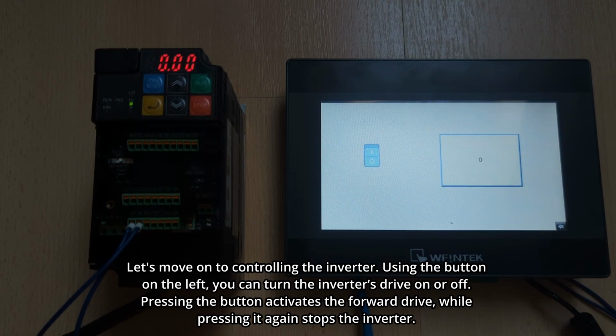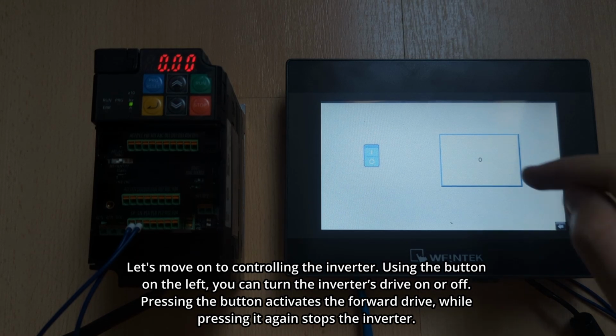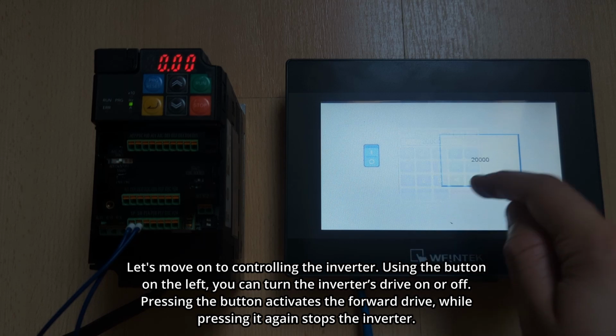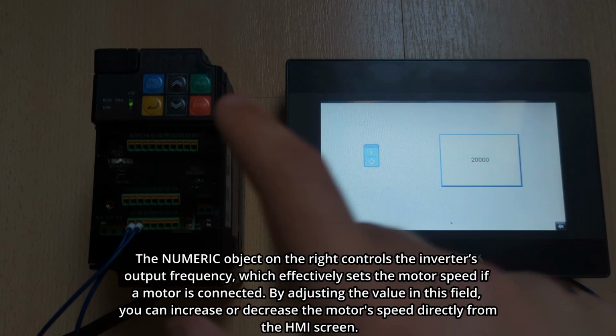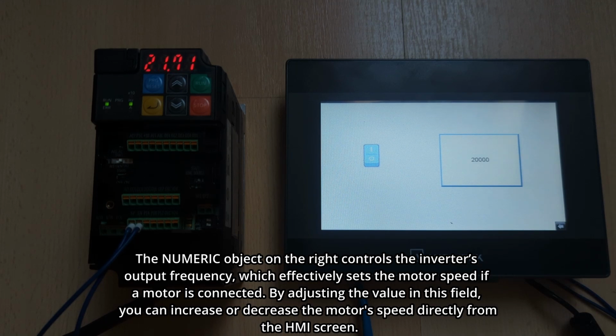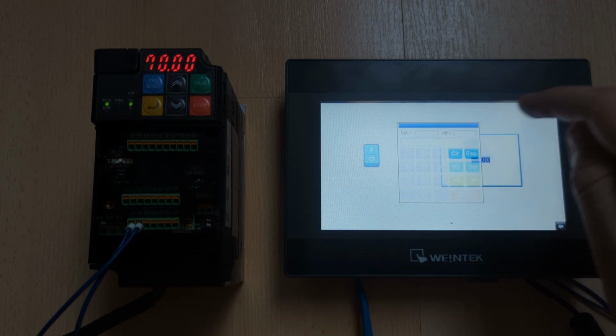Let's move on to controlling the inverter. Using the button on the left, you can turn the inverter's drive on or off. Pressing the button activates the forward drive, while pressing it again stops the inverter. The numeric object on the right controls the inverter's output frequency, which effectively sets the motor speed if a motor is connected. By adjusting the value in this field, you can increase or decrease the motor speed directly from the HMI screen.